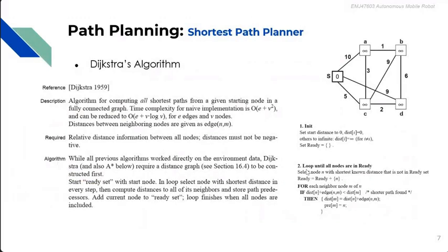Okay, let's go to the calculation part. There are two main path planning algorithms that you learn in this course. First one is Dijkstra. Second one is A star, right? So let me ask, which one is more efficient? A star. Why is A star more efficient? Why is A star better? Faster. Why? Less operations. Okay, why less operations? You don't need to find the values for each cell in the map. Okay, why don't you need to find every value for each cell?